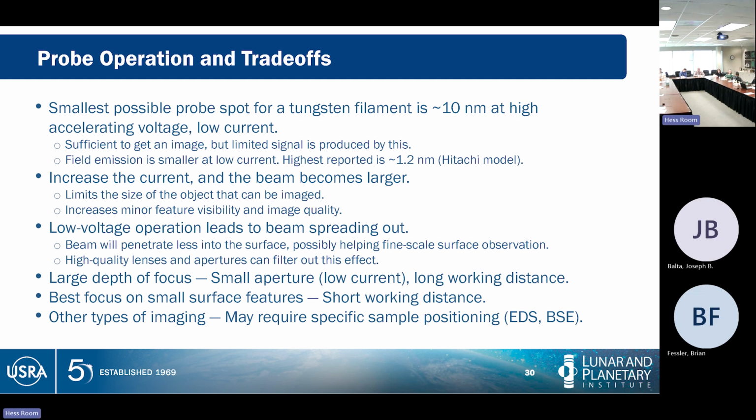As you adjust your settings, the beam responds to this. If I increase my probe current by bringing more electrons through, the beam becomes larger. Well, a larger beam limits the exact focus that I can get with my SEM. But a higher current and larger beam will allow me to brighten things up so I can see more features and improve the image quality.